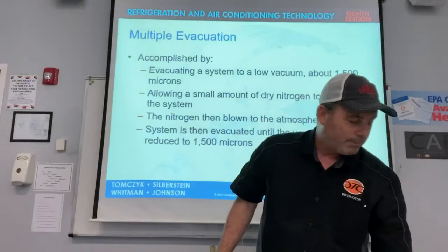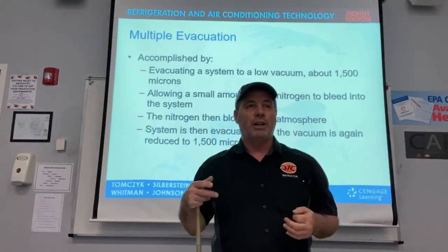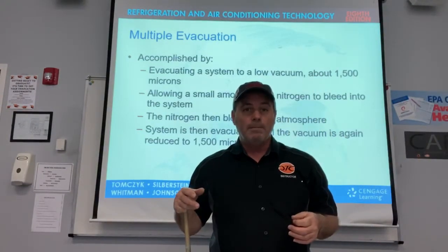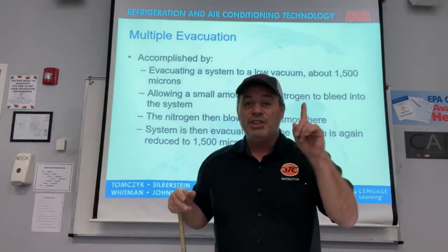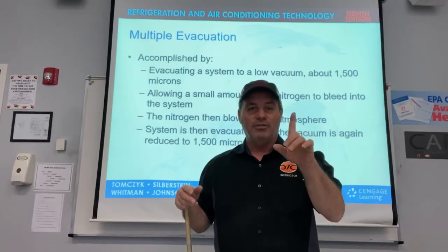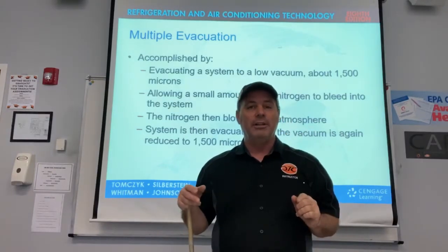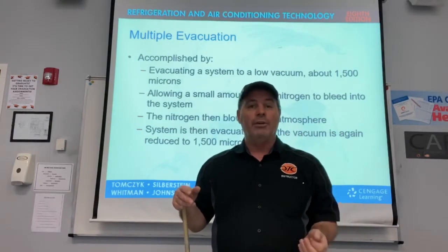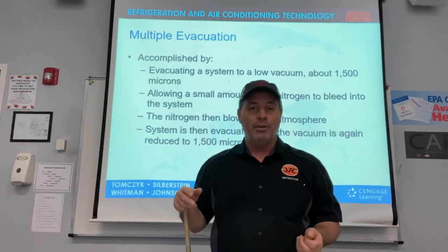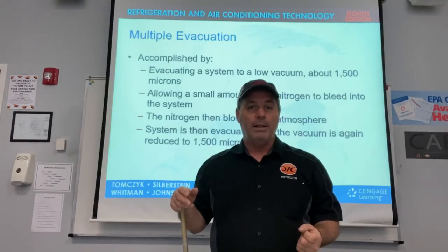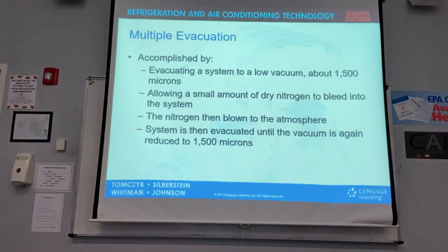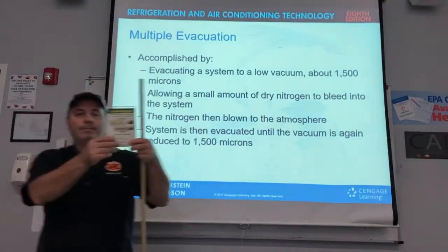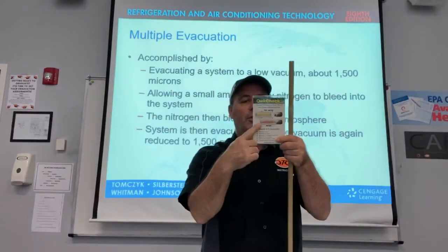I was trained that if you put a suction line dryer on a system and a liquid line dryer after a burnout, you have to get an HH dryer, it'll say HH, high acid dryer, and you leave it on the system. You come back between 24 and 36 hours, and you put another dryer on there. Okay? You check the refrigerant in it with a little leak test like this. See that? If it's yellow, it's good. If it's orange, it's not.